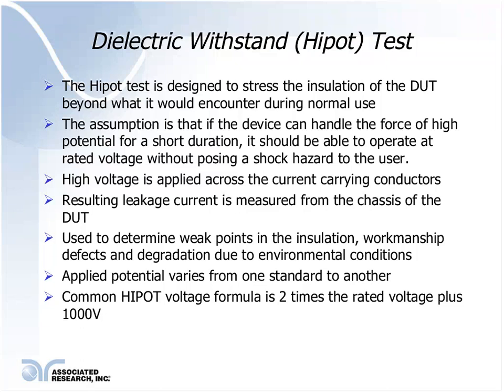And because this test is so versatile and can detect a number of insulation failures, it is generally specified by standard agencies as a 100% production line safety test.